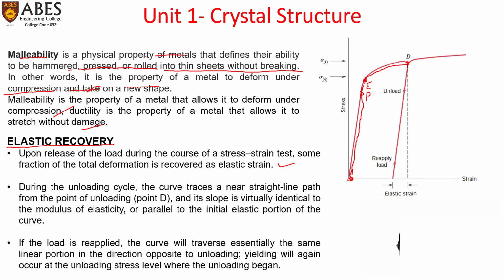But once it reaches the elastic point and beyond, plastic deformation gets started. If you unload after this point, it will not return to the origin, but will come back parallel to the slope of the elastic region, and it will stay here, meaning there would be a permanent strain for that load. Even if we remove the stress completely, there would be a certain plastic deformation denoted by this strain.